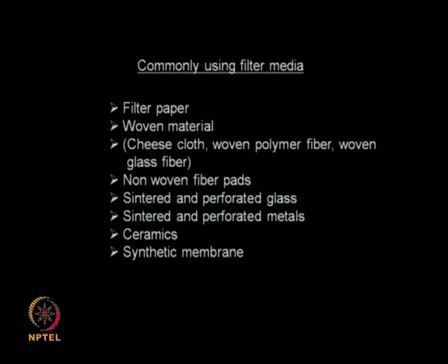Sintered and perforated glass, sintered and perforated metals. If the solids are going to be abrasive, it is better to use a metal type of filter medium. Ceramics, if you are talking about high temperature filtration, ceramics will be able to withstand these high temperatures. Membranes, synthetic membranes, different types of membranes, hydrophilic membranes, hydrophobic membranes.